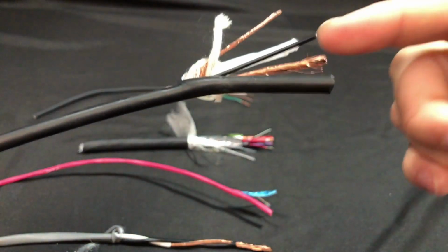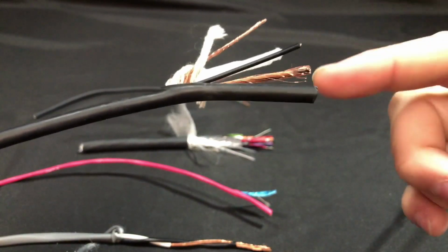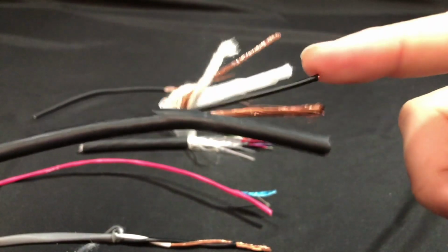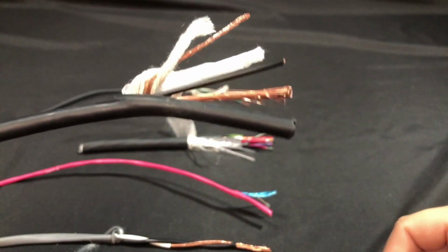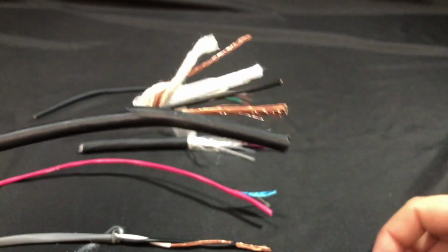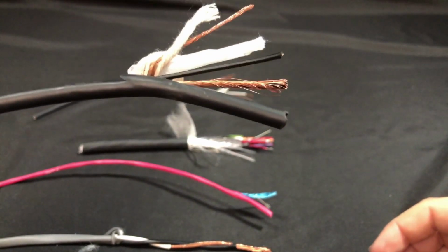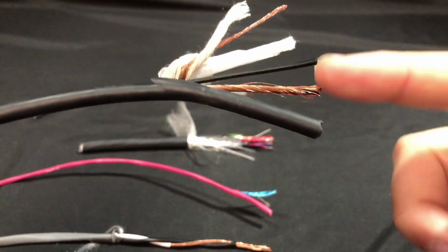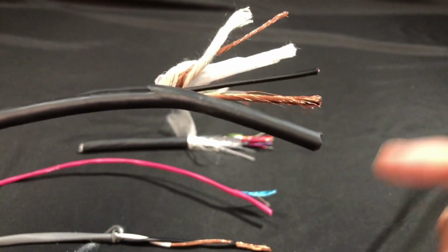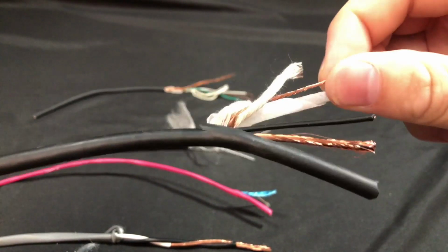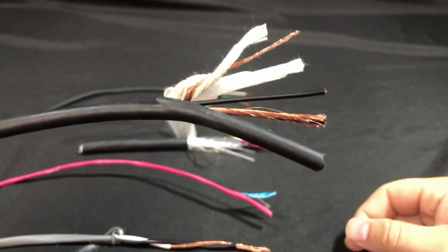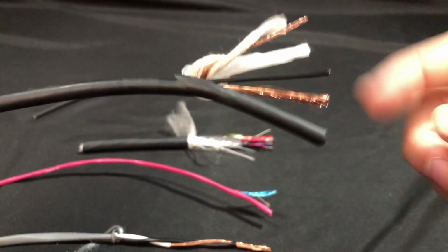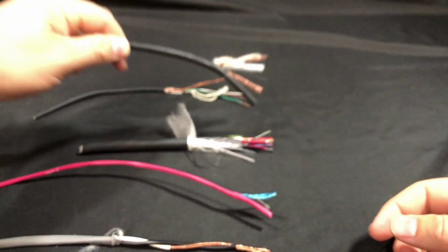So this cable had 2 conductors, both were wound with their own separate braid, which means they're isolated from each other from crosstalk, and from the outside from electromagnetic interference. But this is a microphone cable, so it needs to be a balanced signal, so it needs to have 3 conductors. So this one only has 2 built in, and you have to use one of the braids as the ground conductor, which is not the best. So this one's a little cheaper because it doesn't have a dedicated one.